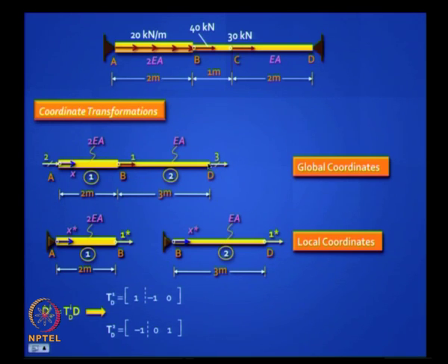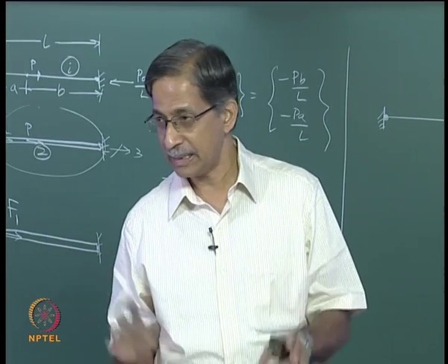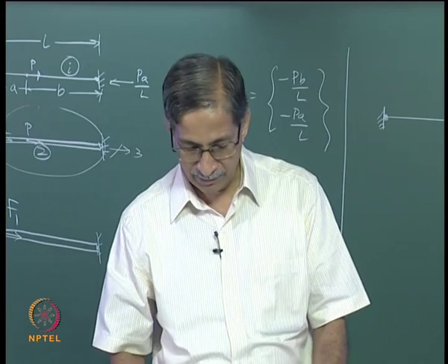Lastly, when you pull D3 equal to 1, element 2 will get elongated, and element 1 remains unaffected, so it is 0, 1. Is this clear? It is as simple as that. In 1D structures, you will have only zeros and ones, no sin theta cos theta here because theta is 0. Is it clear? It is very easy. I hope there is no confusion here, it is straightforward.